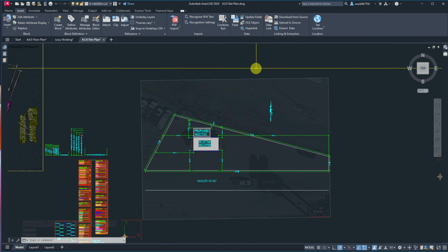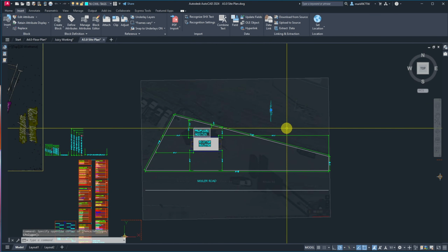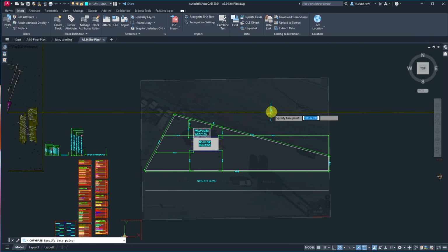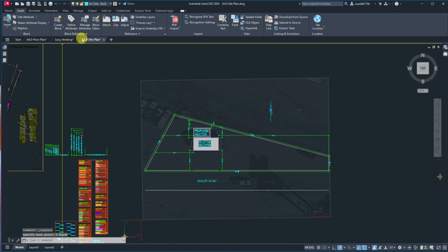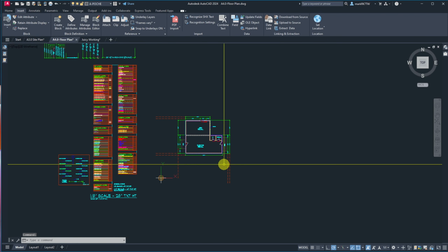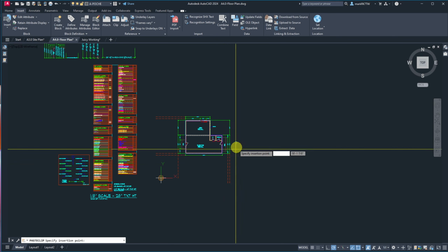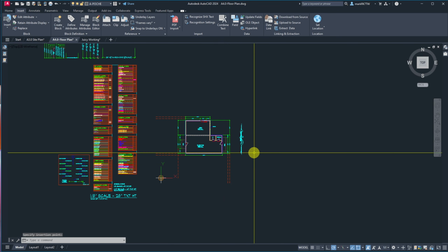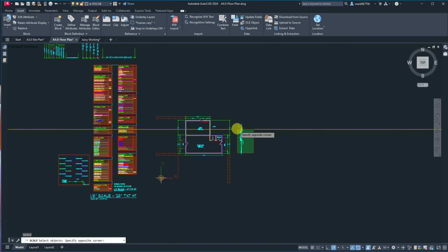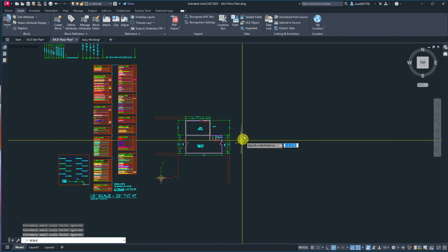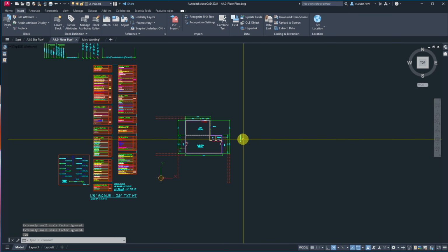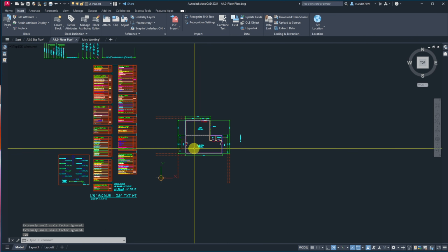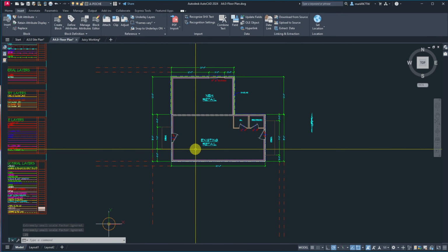The addition is going to be on the north side. So let's just grab that thing. Control Shift C, pick that point, come back to site, put it out front, floor plan, Control V, and let's drop this guy in there. Now it's huge, so let's bring it down about 0.25. That should be plenty.